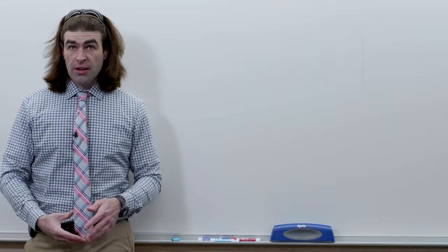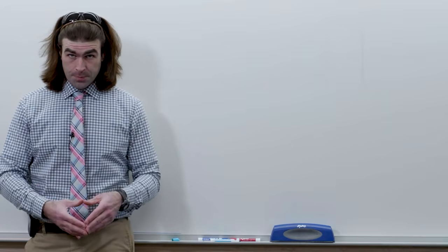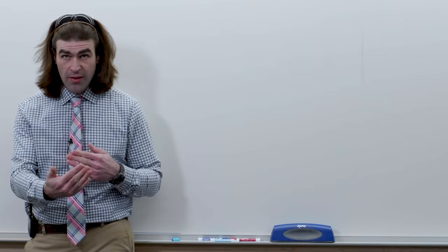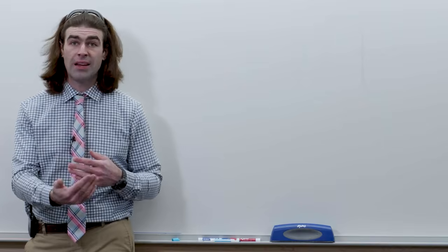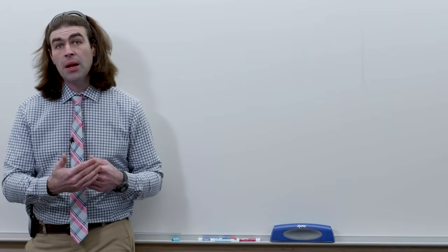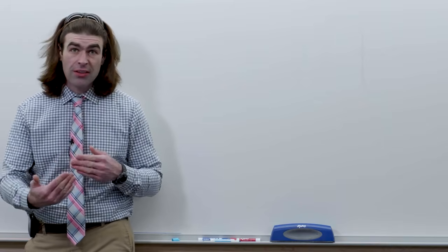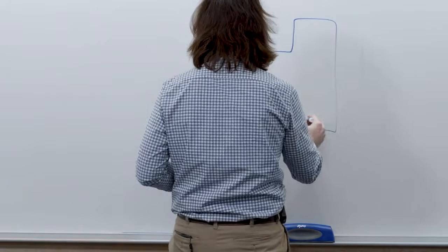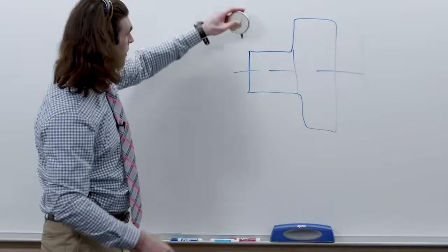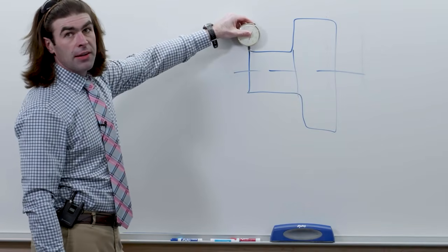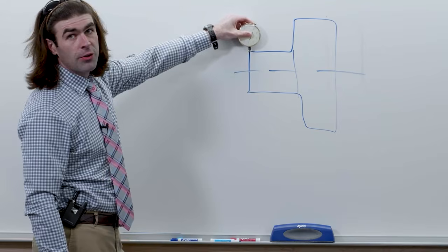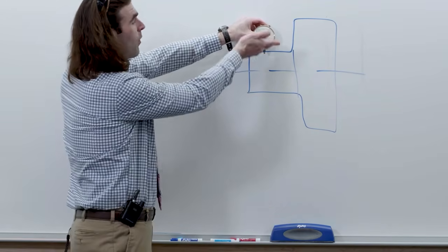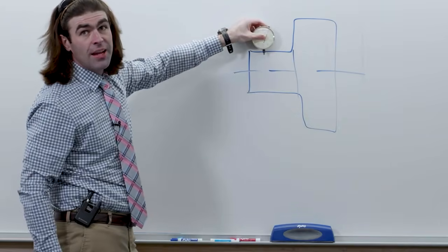The check for this is much more difficult because in order to make sure it's straight along the length, you can't move your indicator. The indicator needs to move parallel and the same distance from the axis of revolution. So that means that if we lock our indicator in here, spin it 360 degrees, when we check the next spot, the indicator cannot move away from or toward the datum axis.